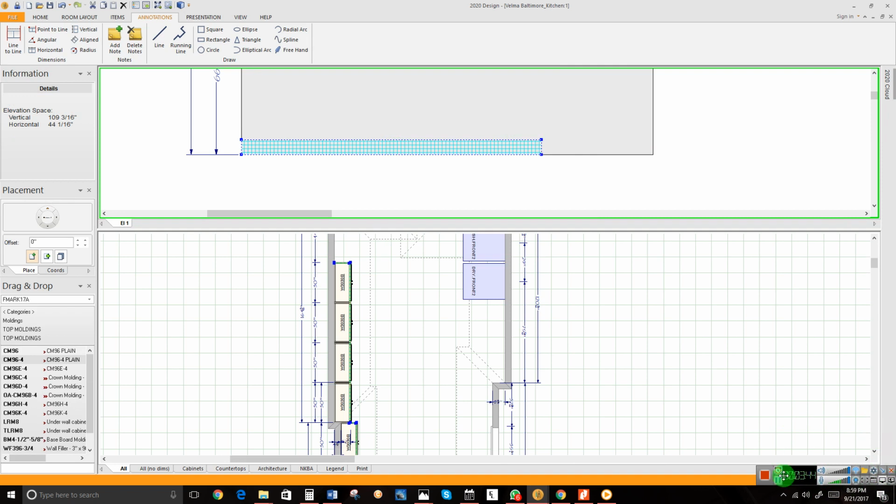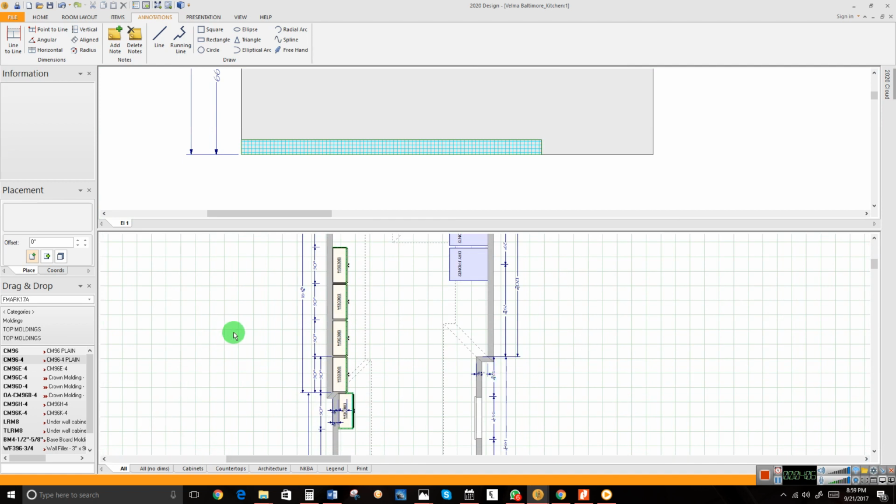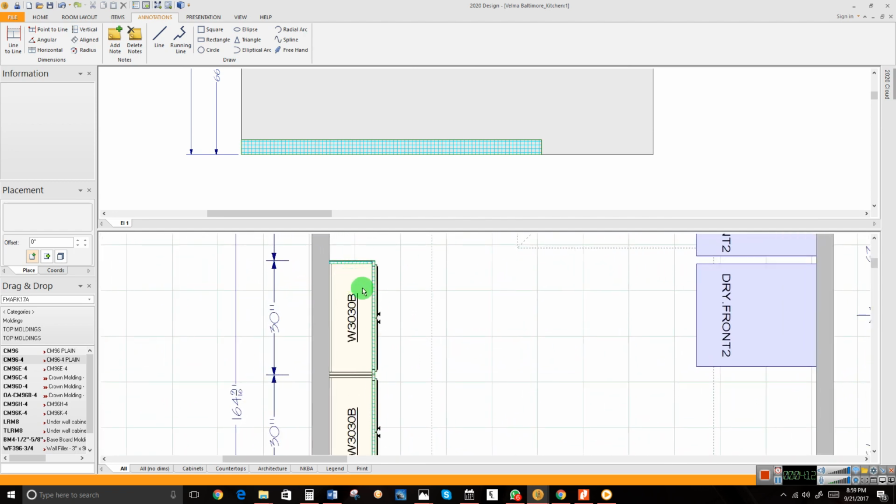2020 has a new ability in 11.8 to show you what the issues are. So once you wait for a second, it's going to pop up. You see that, right? What's it saying? It says length of section exceeds maximum length of model chosen. So how do you adjust this one so you can get proper pricing? Fastest way to do it. Each molding length is actually 8 feet long. There's some that can go to 10 feet long, but this is how you resolve this problem.